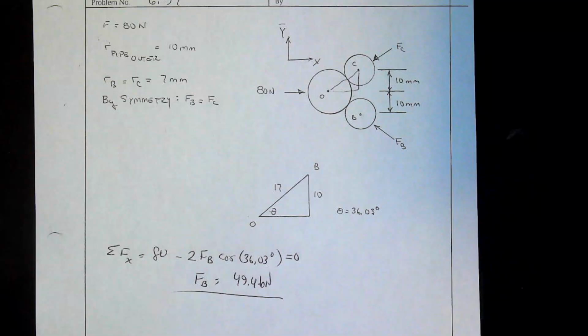Summing forces in the y, we know that's equal to 0. So this is 2512, and then we need the sine of 60. And then we'd have minus FAB sine of 45. And that's it. And that leaves us FAB at 3076 pounds.